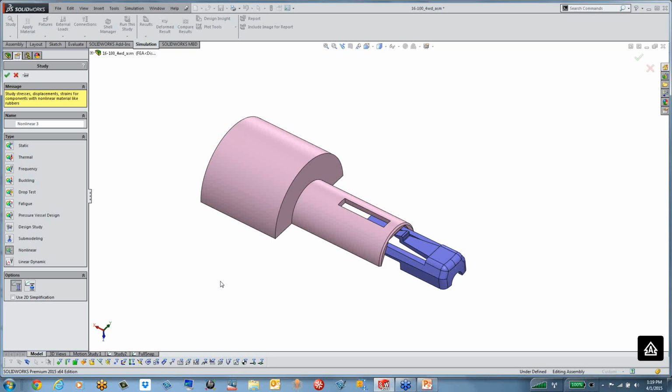Like I said before, there's a lot of iteration that goes on behind the scenes, and for that iterative solution, we want to make sure that we get the right answers. The program has to take smaller time steps, especially when the contact areas are really small, and we need to capture the exact sliding operation, which requires a nonlinear analysis.